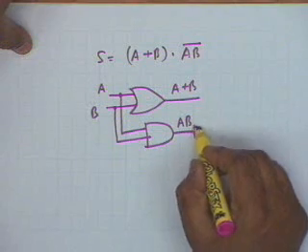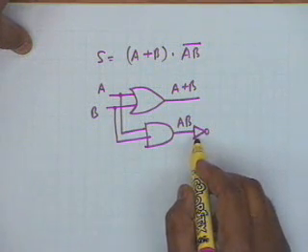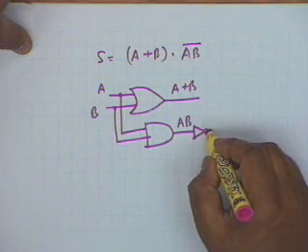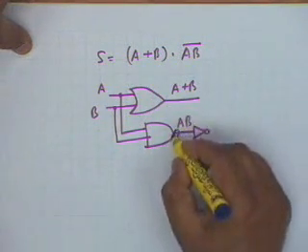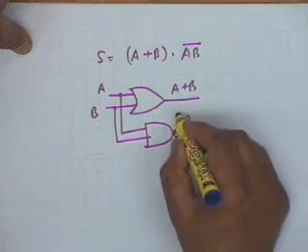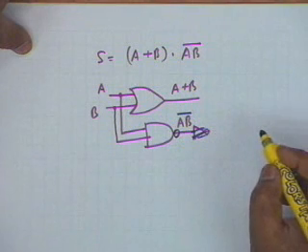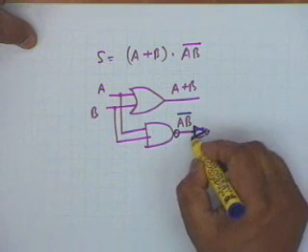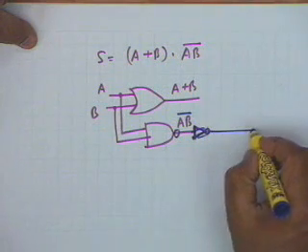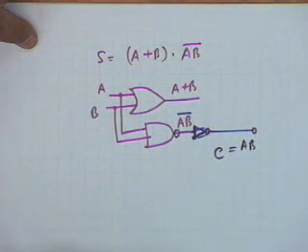Then a NOT, or I could combine the two. All right, let's take an AND, then this is AB bar, and therefore either way it's okay. We have to use another NAND to be able to get AB, which is equal to C.